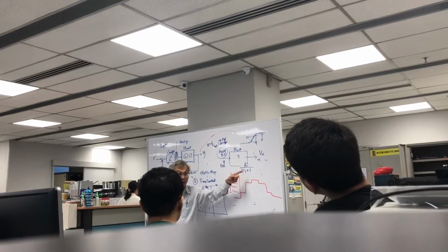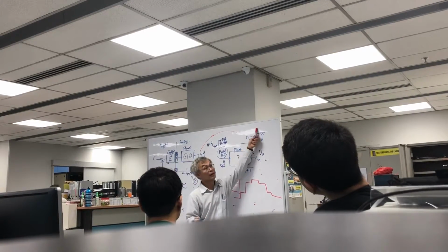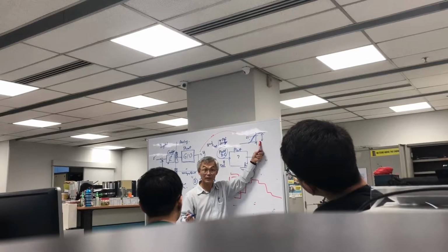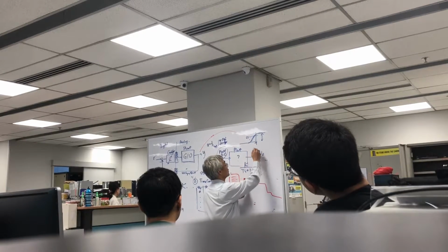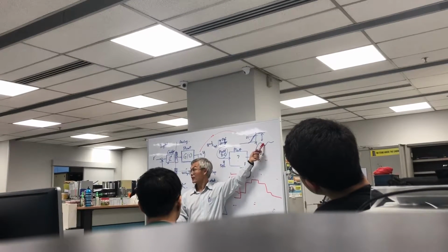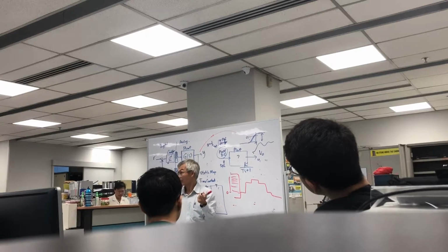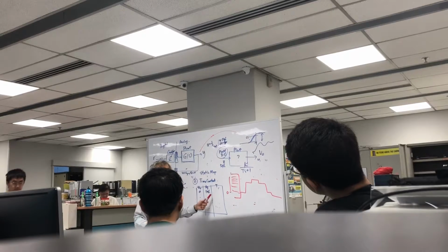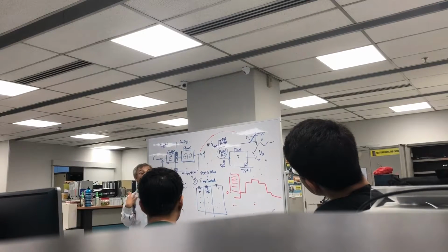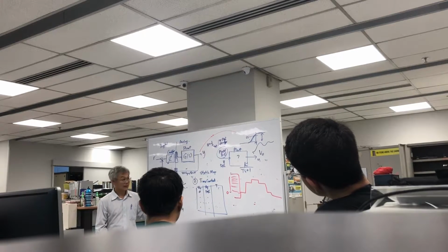What is the step response? Does it look like a first order? And then you can estimate the time constant. Or does it look like this? Then obviously the first order assumption is not a good assumption. So you see for yourself, and then you show me. Is that clear? Open loop test: do a static test, do a step test.